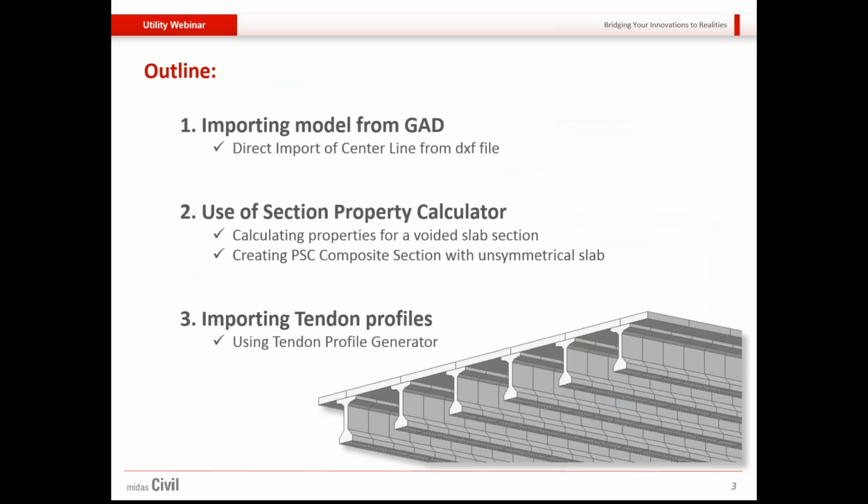So now, no matter how big or small a project might be, the GAD of the same would always be available to the design engineer. After all, that would be the reference drawing for the structural designing to be done. Most of the time, this would even be available in editable soft copy format like DXF or DWG, which could be easily converted into DXF by a drafting software. So Midas supports the import from such DXF files in several ways to assist the modeling, as we will see today. So we'll be importing the center line for PSC I girder bridge.